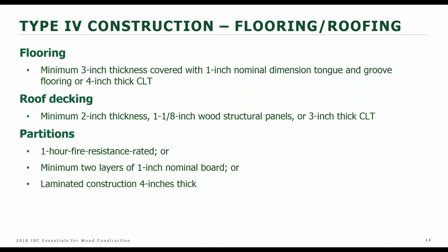You are permitted in type 4 to have a little bit of light frame in your partitions, as long as the partitions are rated for 1 hour. And so there's an exception there. Otherwise, all heavy timber dimensions.